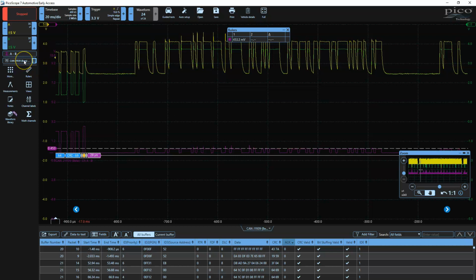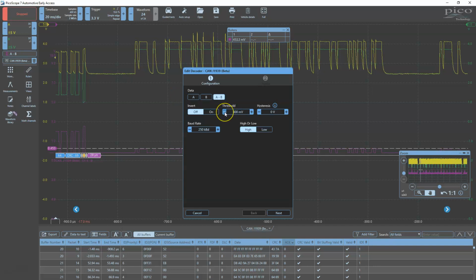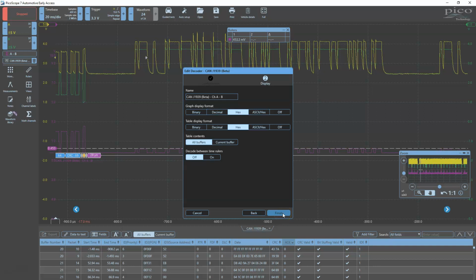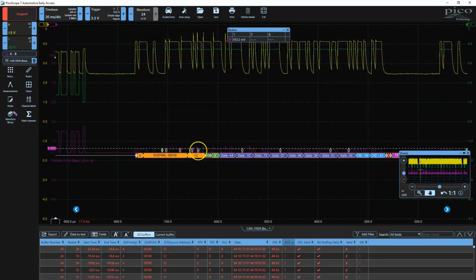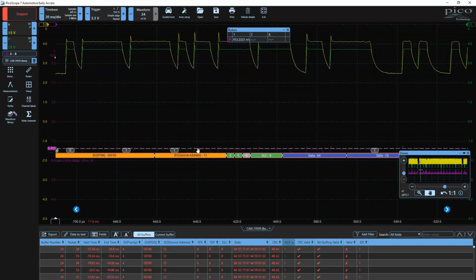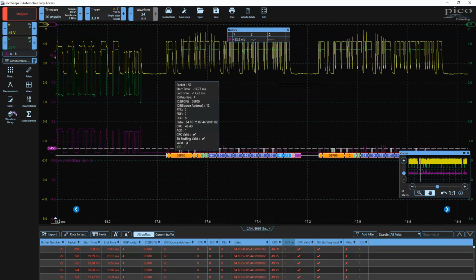Being able to adjust this threshold, though, is great. This is for a tool such as this or anything which uses it. Otherwise, I wouldn't know which device this is. Once again, I can't find out specifically or exactly. It may not even help me that much because the device description isn't that great. But for the most part, I know the devices I've got on the bus, and in this case, I knew that it had something to do with the fuel system, so I'm pretty much able to narrow it down. It was the fuel pump.